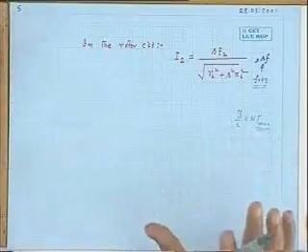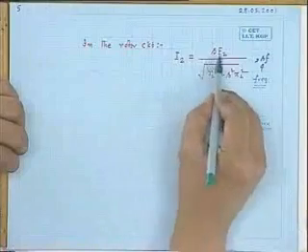Here Imax is the maximum value of the current, and no frequency comes. The amplitude of the MMF is decided by this. You pass 50 Hertz current, suppose 5 ampere is drawn, whatever the amplitude of MMF, if you pass the same amount of current at 25 Hertz, the strength of the field will remain the same.